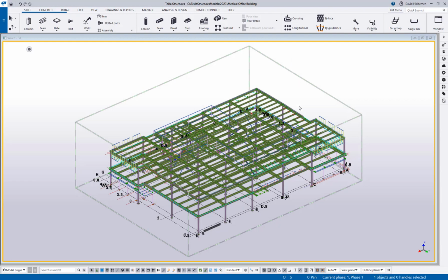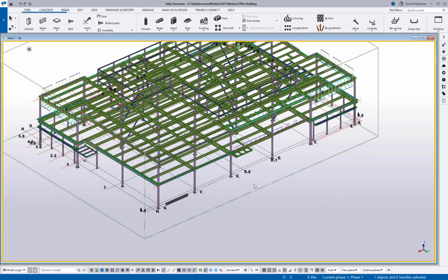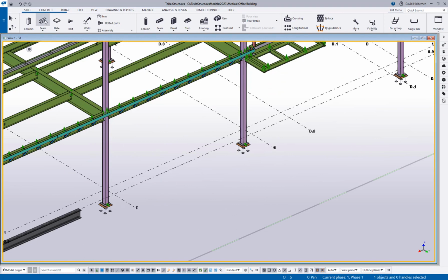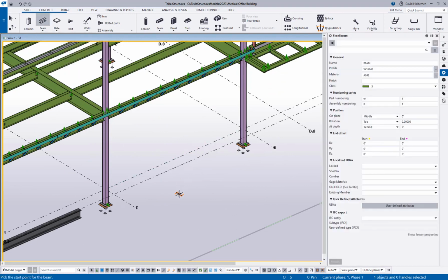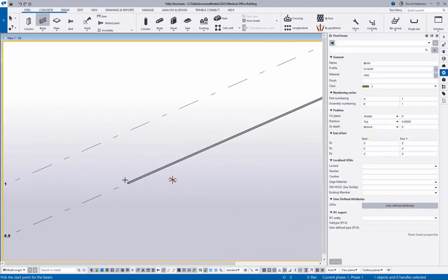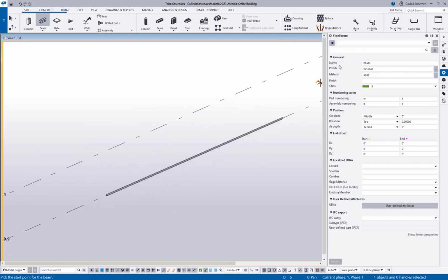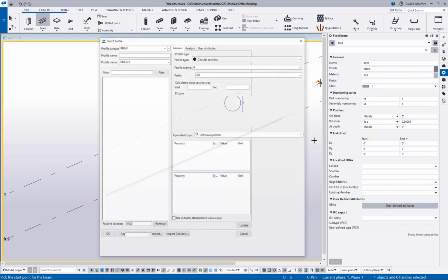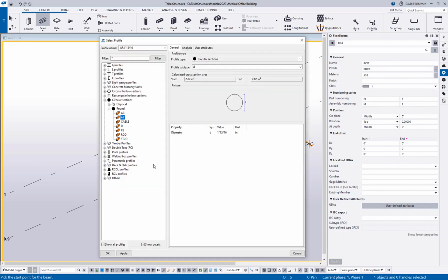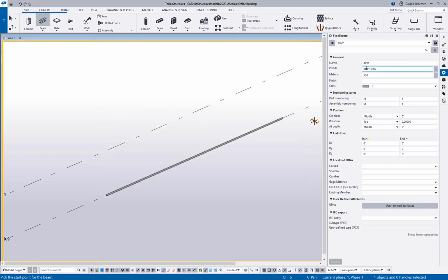All right, so through the magic of editing, I've got the model reopened now. So let's go ahead and walk through those same steps from a moment ago. So there's my 1/2 inch diameter AB profile. So let's come in here and load rod again. And we'll go ahead and open this up, and you'll see that now I've got an AR in addition to the AB and the RB and whatever else that I wanted to create. So this now works like every other parametric shape. If I wanted to make an AR 4-inch diameter, I can make an AR 4-inch diameter.